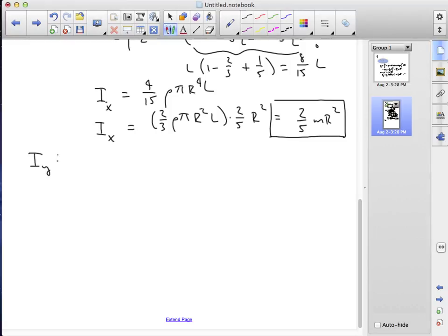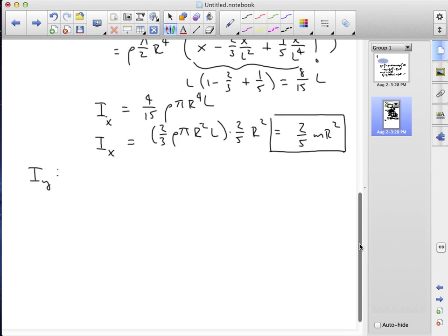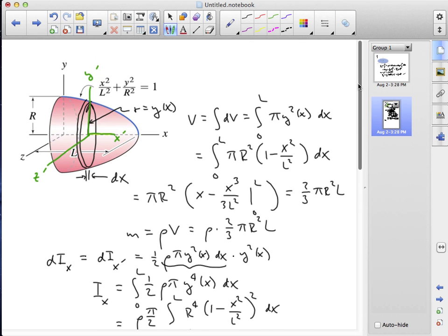The calculation of Iy is not as straightforward because the center of mass y prime axis for the differential disk element is not coincident with the y-axis of the problem coordinate system. So let's go back up here for just a second. And we'll make a note here that all the material points in the differential disk element are at the same distance x from the y-axis.